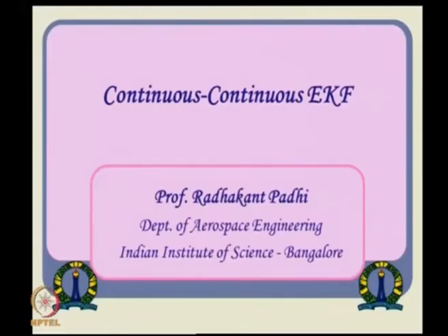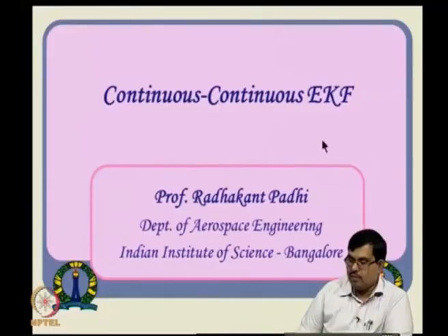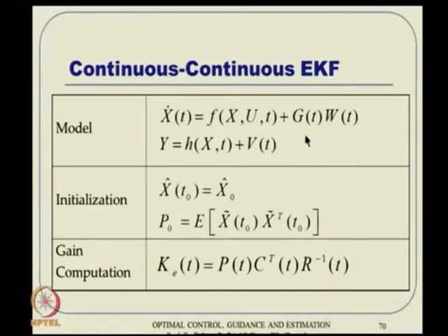Anyway, finally, there was an idea that all this we studied because of understanding the so called EKF or extended Kalman filter. That is what is used heavily in practice. So, here the system dynamics is nonlinear, and the output equation is also nonlinear. Then we have this idea of continuous EKF, in the sense that system dynamics is continuous and output is also continuous. But if you generalize that, we can also have a continuous discrete formulation where the system dynamics is continuous, whereas the output is discrete.